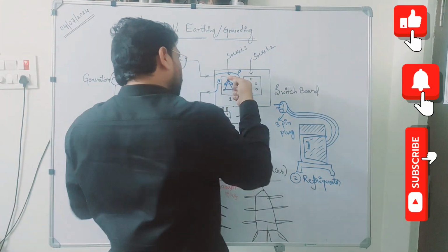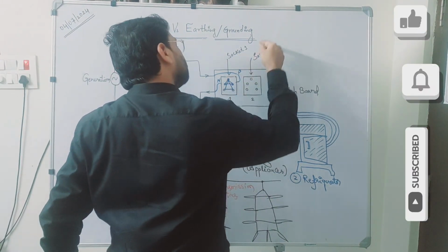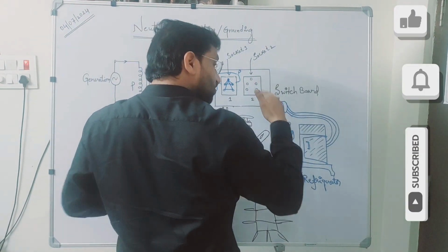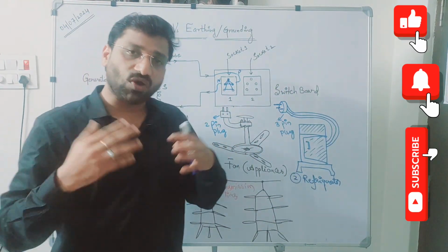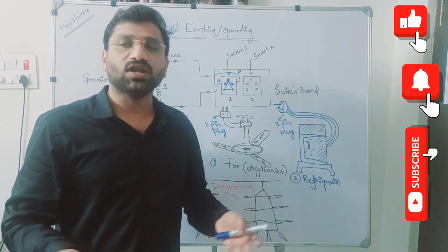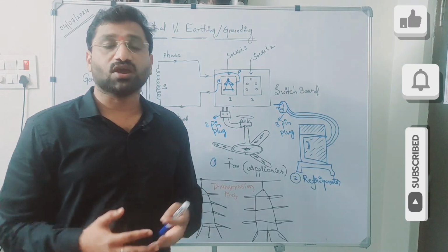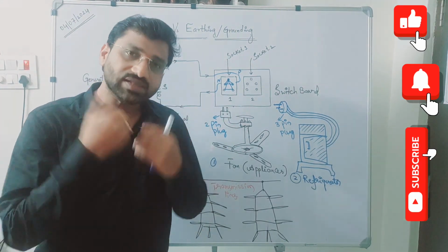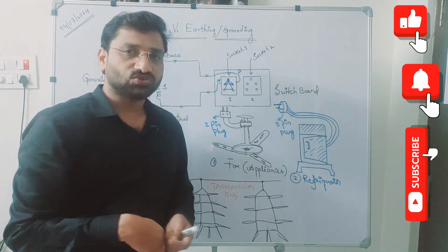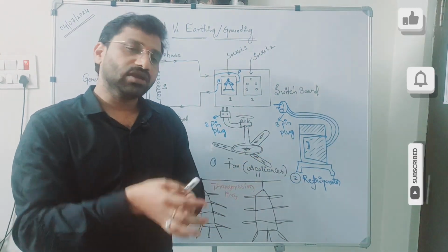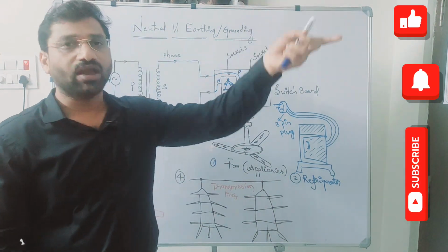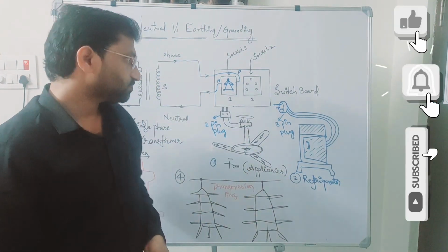Now, one lead comes out from this hole, and one lead comes from this hole. And like this, if you have many switchboards or sockets in different rooms, say in a triple bedroom house, however many sockets and switchboards you have, from all of them you can take out the ground wires, put them together and connect them at one point, and connect that point to a rod and insert it into the ground at the back or in front of the house.